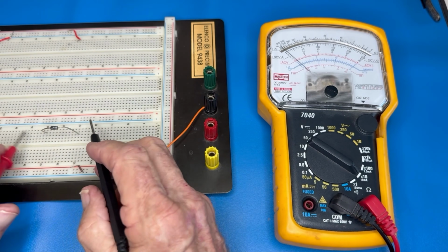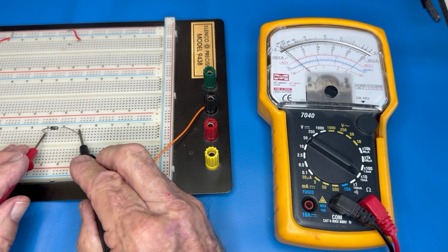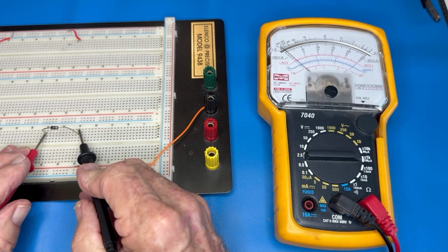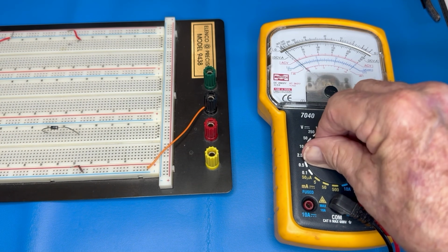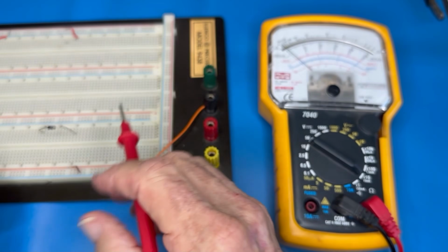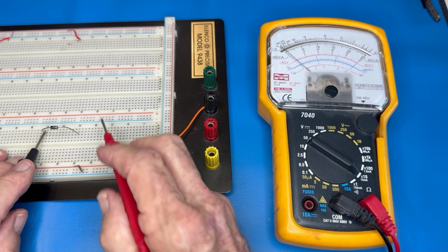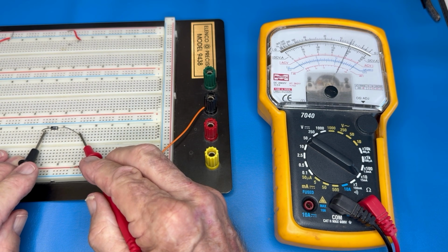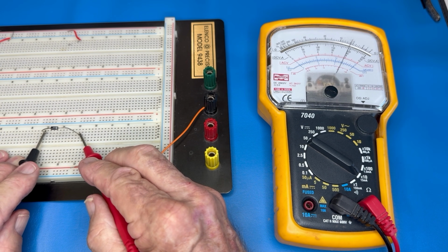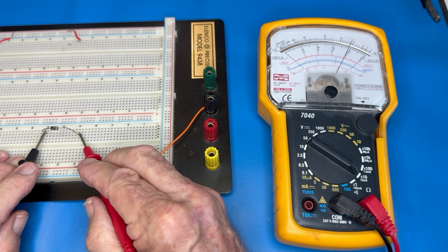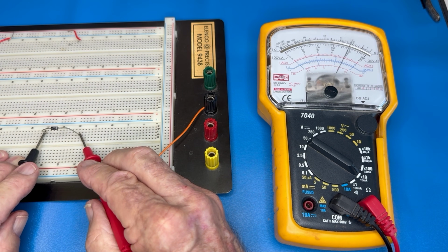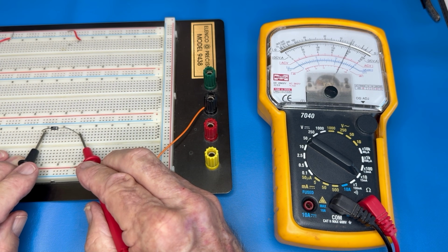Okay, so we'll do a reverse biasing on the diode. We shouldn't get any conduction, and we do not. And we can go up to like 1K range, no conduction at all. We go back down to the times 10. We do a forward bias by putting a positive voltage on the anode and having the negative voltage on the cathode, and here we got conduction. So the depletion region reduced down to absolute zero. 0.7 volts is being dropped across this silicon rectifier. If it was a germanium rectifier, it would be 0.3 volts.